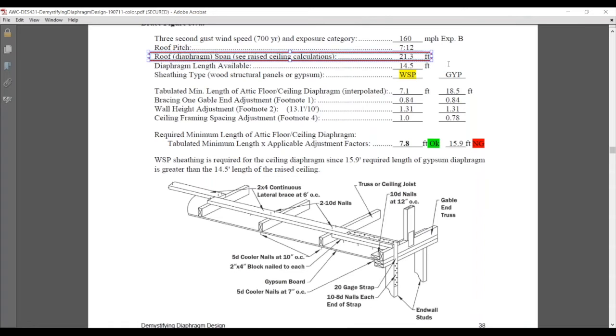The other issue that we're going to see in a second is that if we want continuity there at that diaphragm, we're going to have to frame the studs up to that diaphragm 13 feet from the floor, the second floor. So we're going to have 13-foot studs, which means we're going to pick up some extra tributary area of those studs. They're no longer 10-foot studs that we assume in the rest of the building.